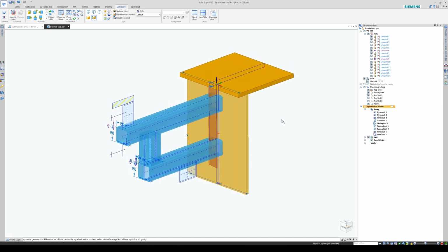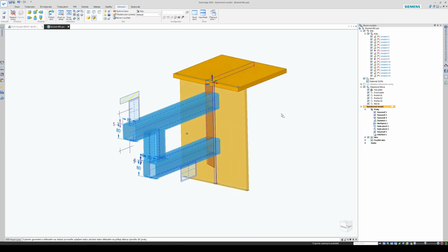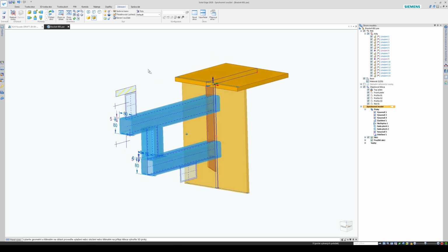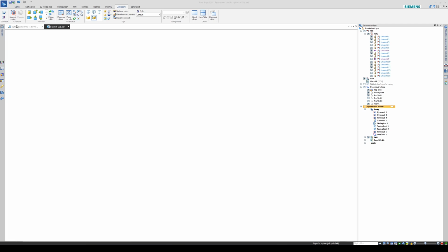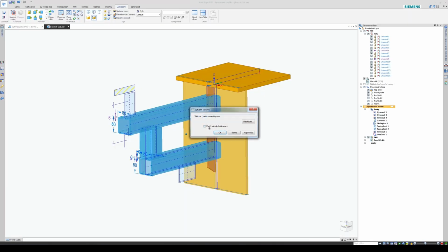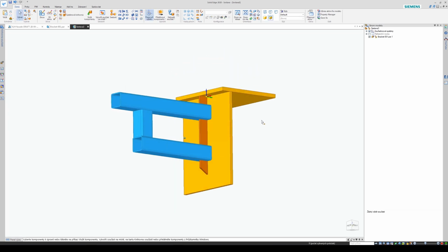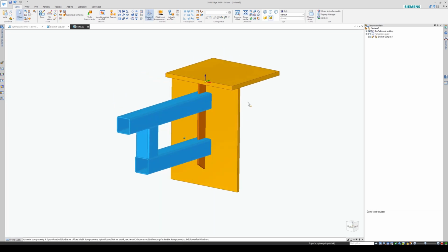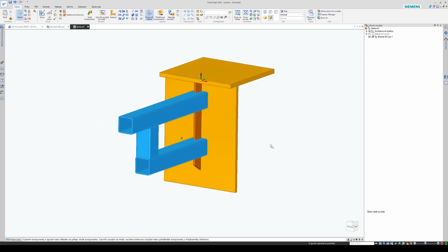So if I want to show someone, or if I want to view this one shaded or all shaded, I need to open it in assembly. Don't close the actual document because I want to continue working on it. I can later close it, but for now I just want to stay open. And here we have it in assembly environment, fully shaded.